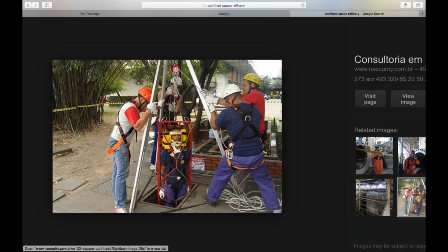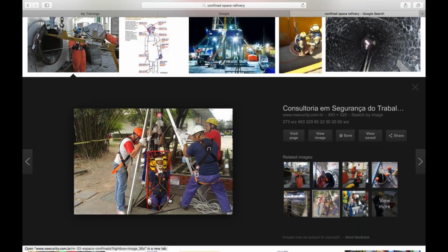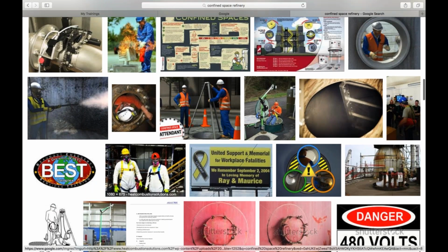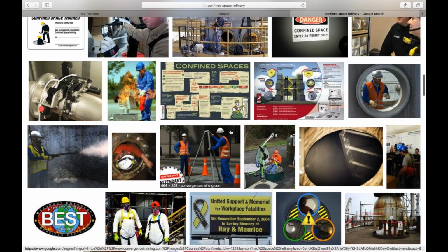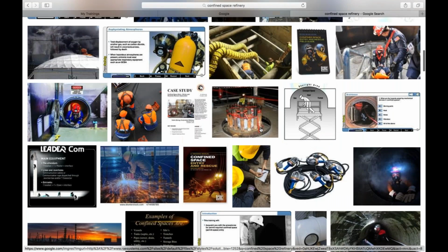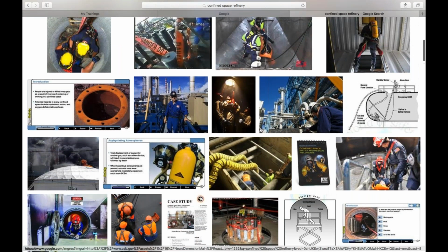Okay. Also, all impellers, agitators, or other moving equipment, they have to be locked out. So we have to go back into our lockout tagout process, depending on what's inside that unit or that piece of equipment, right? To make sure that no employee is going to get sliced, diced, ripped, twisted, whatever the case is. Augers, agitators, whatever the risk is.